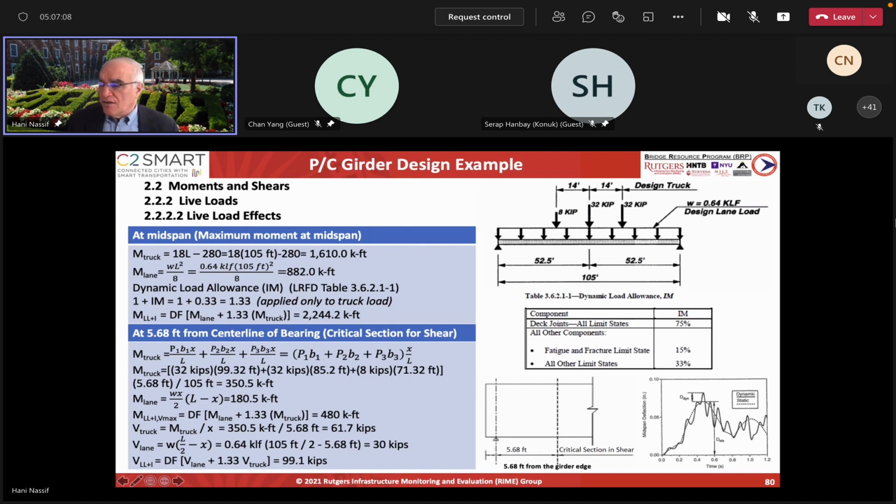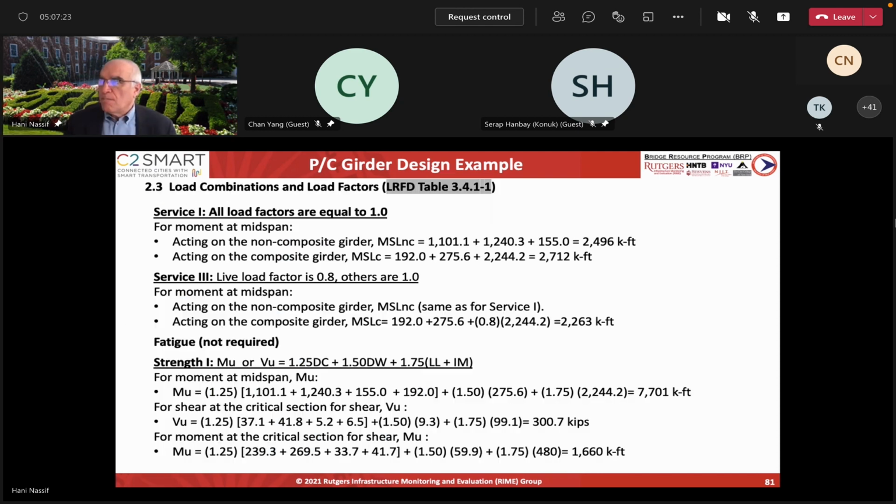And you also find it from the lane, same way. So this is the total, the shear, sorry, from both of them needs to be calculated. Next, now you found out what is at each section. You found out the moment, you found out the shear, after you distributed everything, so you have the shear per girder and the moment.